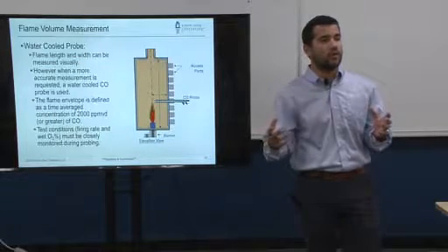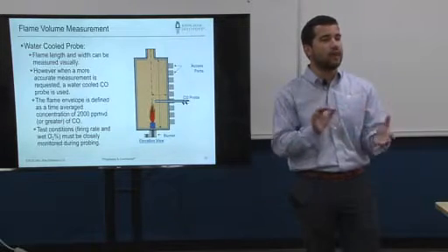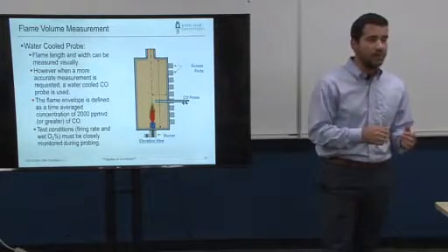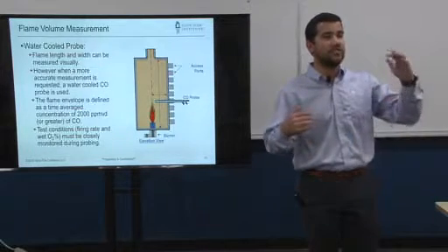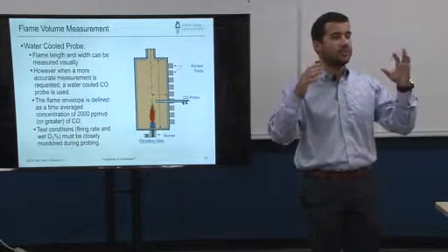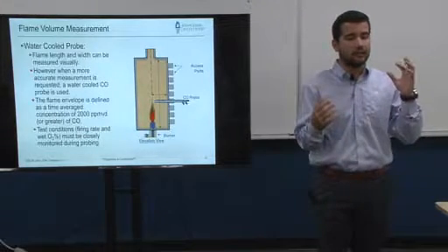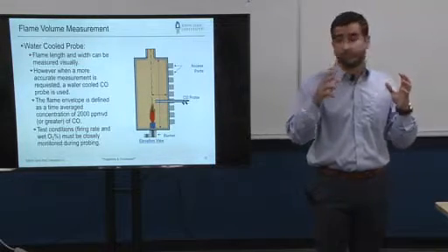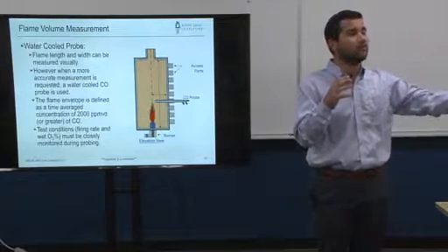Once we do that, if we find any issues with it, we tend to tailor gas tip geometries to get the final flame shape that we're looking for. Then you go to the test, you get your test done, and you compare your CFD flame characteristics with your tested flame characteristics. Sometimes you do a little bit of tailoring on the CFD, like reaction models, for example, in order to match your burner testing characteristics, and then again you apply it to the full heater.